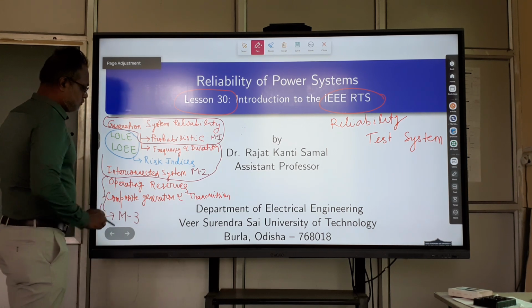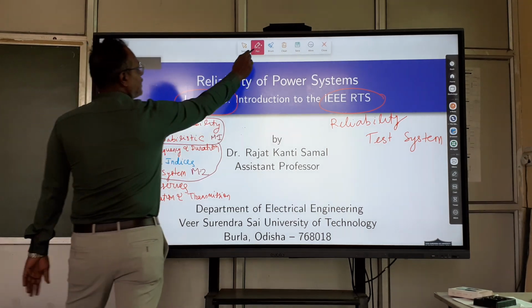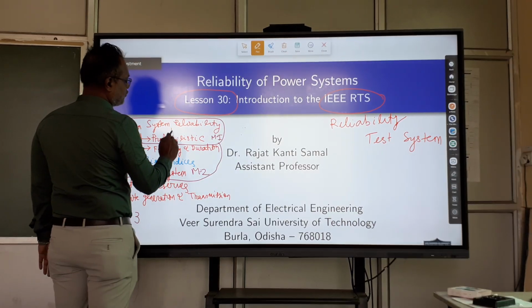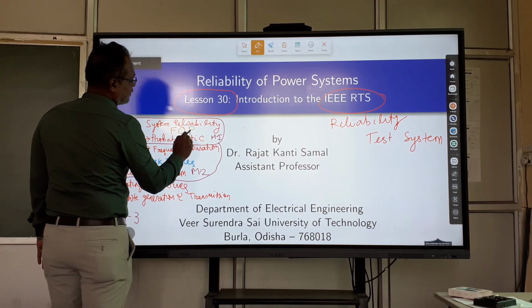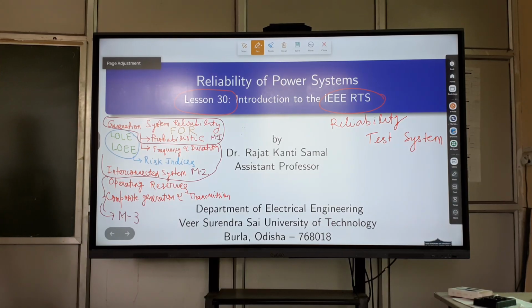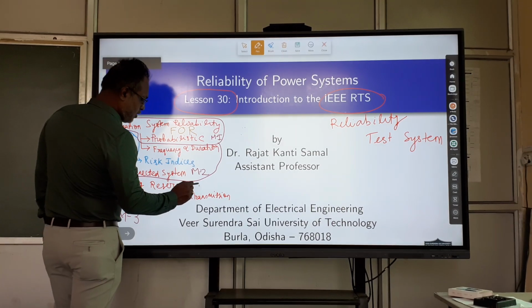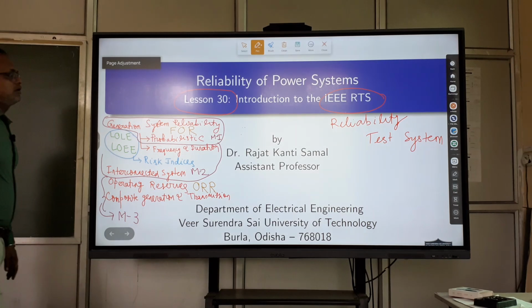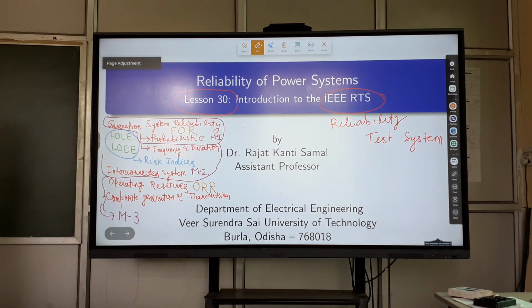And also we used a term known as post outage rate for generation capacity reliability. But when we discussed operating reserves, we used the term outage replacement rate, rather than post outage rate, because reserves are about replacing the units that are out.